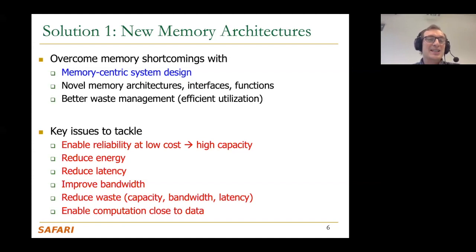Can I access faster, while being reliable, at low temperatures, for example? Because at high temperatures, maybe the cells are leaking data very quickly and things are not working as robustly. So I need to give it more time to access memory reliably. But at low temperatures, I don't need to access memory at the same latency that I require at high temperatures. So this is another realization that there's a lot of waste in terms of latency, and we're going to talk about that also.